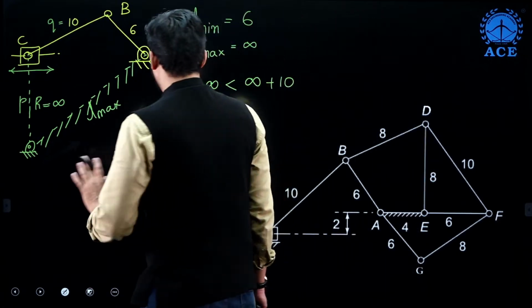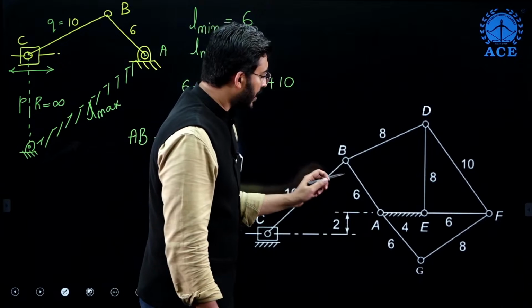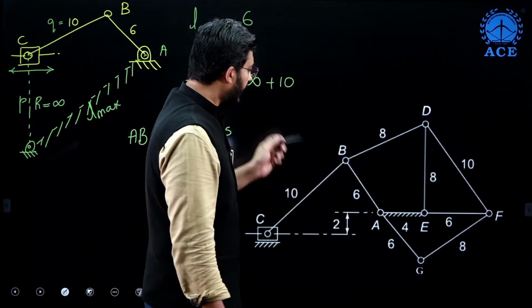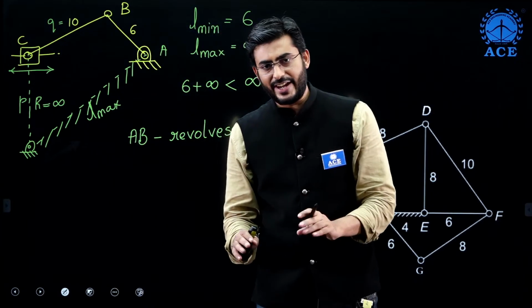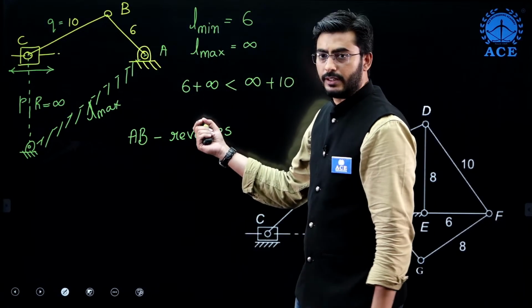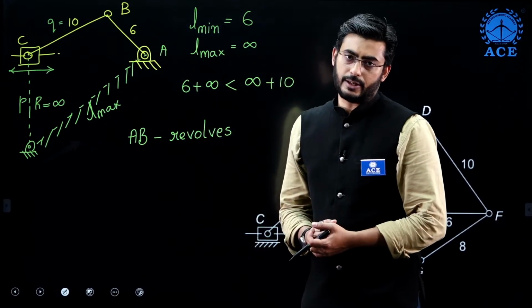All right. Similarly, if we consider another linkage, here Grashof's law is getting satisfied, and we are able to locate the link which is completing circular motion.